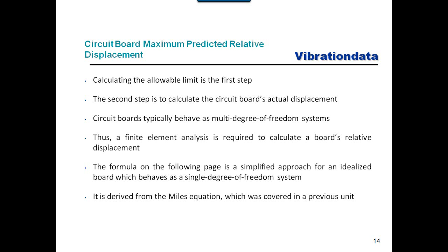So we can, for the most part, get away with some simplifying assumptions. But having said that, yes, there are exceptions. So if there's any doubt about what I just said, please do a finite element modeling. If you can do some type of modal test on your circuit board, that's great too. That data is useful. But we're just going to go ahead and assume a simple single degree of freedom system.